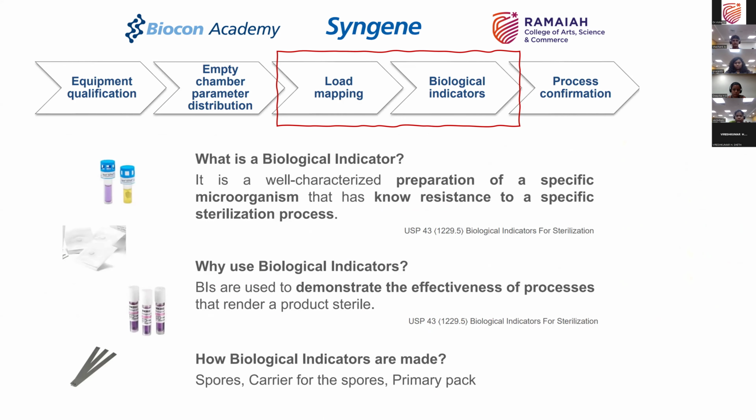Then you will do what is called load mapping, and we will talk about biological indicators. Load mapping we have again discussed a bit during autoclave cycle development. We talked about the load patterns: fixed load, fixed positions; variable loads, variable positions. Generally, in case of VHP, you will not have a variable load, variable positions, because then it becomes very, very difficult on a VHP cycle, since your loads are not distributed.